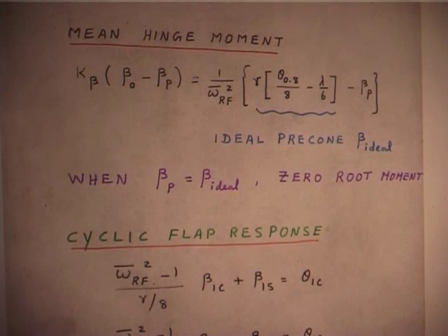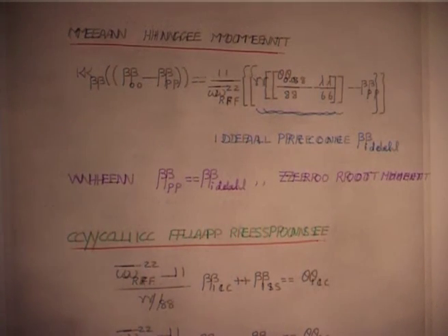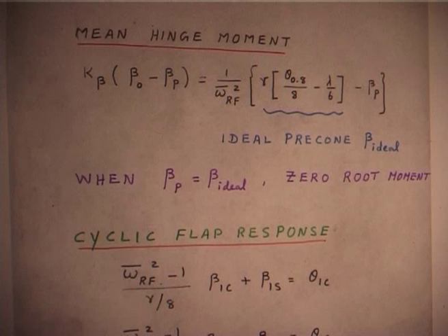That is the idea in actual design. What they do is they will keep a little bit of precone angle, so that you relieve in the structural design. It is purely from a structural design point of view, you reduce the moment that comes at the blade root. Because these are all design features, plus they also have certain influence on the stability.